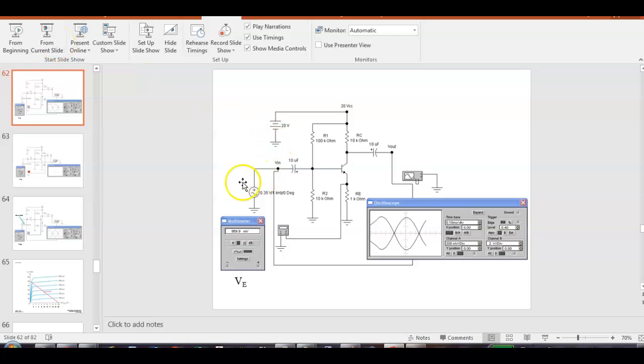So if I was going to try to get impedance matching, that means whatever's feeding this guy would need to have an impedance of around 9.9K. But the problem is that it's so hard to do that because we're dealing with standard resistances. So basically we say, okay, if a transistor's got a high input impedance, I want to match it to something else that's got a high output impedance.